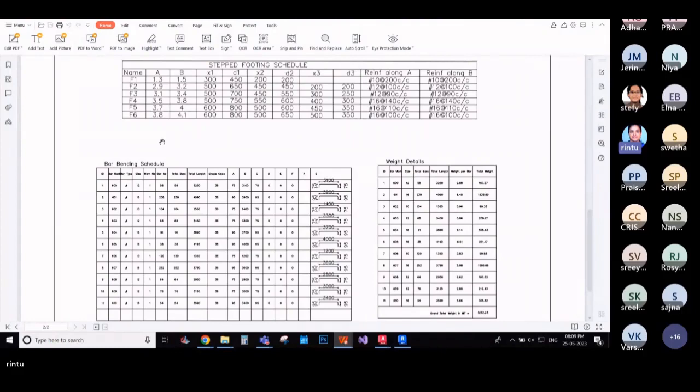But at the site, if the person preparing the rebar cage is not able to cut or assemble the bars properly, what happens? The strength of the structure is completely destroyed. What you expect to stand for 1,000 years will not even stand for 10 years. That is the difference when the bar bending schedule is not properly executed.